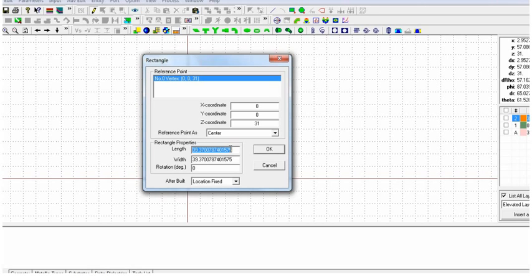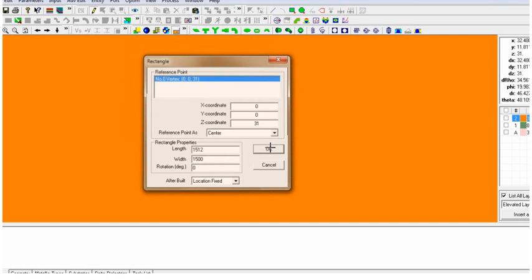So it will ask for the length. Just enter the length parameters. So the length in your case is 1512 mils and the width is 1500 mils. So we are constructing a rectangular patch with length 1512 and width 1500 at the center and with the thickness of 31 mils. Click on OK, and click on all after that. You will see a rectangular patch has been created.